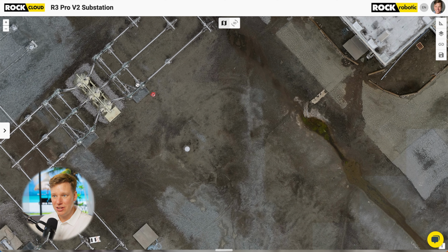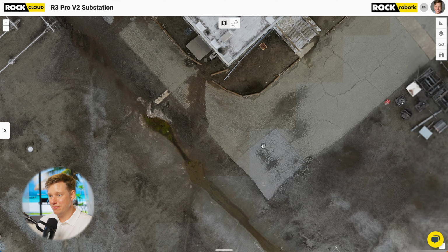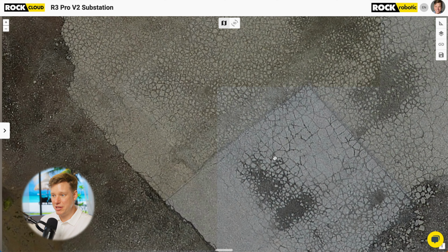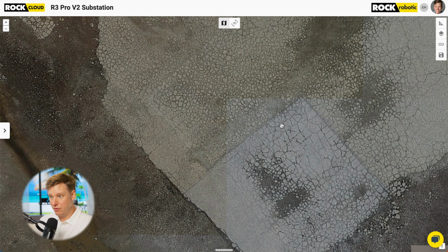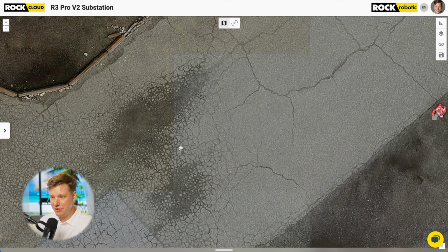And to see the results, things are located in the correct location in that nadir direction, and then looking at the resolution, this is, again, from 45 meters in the air. It's pretty darn spot on. You can actually see this is where 1, 2, 3 photos are all coming together, and everything is continuous, no seam.